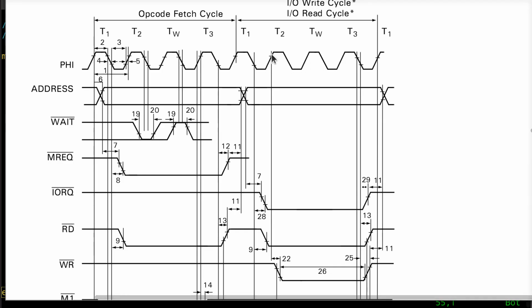So even if I wait until here, and I have this same idea where I have a signal that goes through here, and then it goes false as a result of this falling edge on T2, that's still going to be 25 nanos long, which is an infinite amount of time, relatively speaking, to the performance of our FPGA, even though it's a simple, slow one. That's more than enough time for it to do its job.